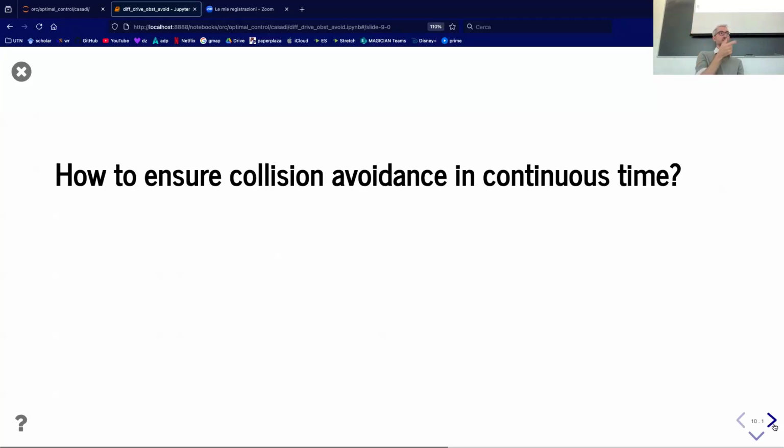But for instance, if you make the time step 10 times smaller and you want to maintain the same horizon length, you need to increase the number of time steps by 10, which is going to increase the computation time by at the very least 10, maybe even more. And you haven't really solved completely the problem, you've just mitigated it. You've made it a bit less obvious. So there's still going to be potential collisions, but it's going to be smaller in terms of penetration.